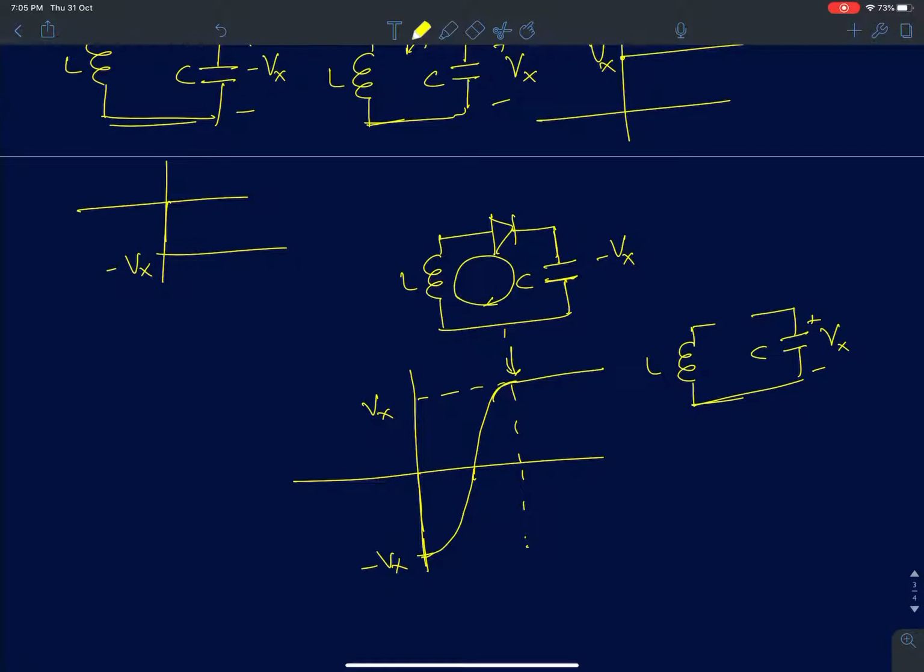So the IV characteristic of the diode is going to look something like this. When your V gamma is 0.5, after V gamma the diode will start conducting, which means the diode at least needs 0.5 volts across it for it to conduct.